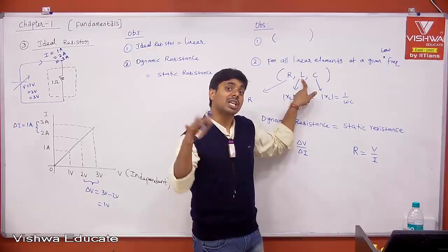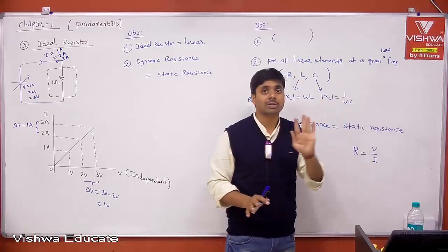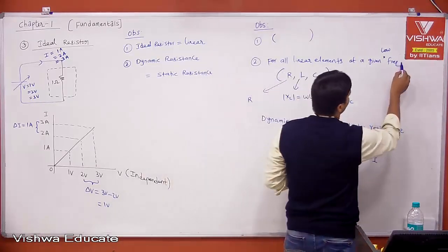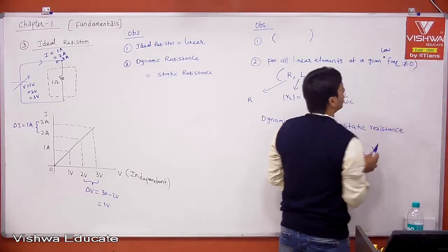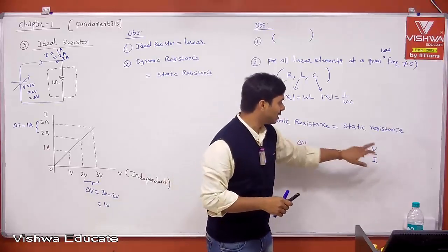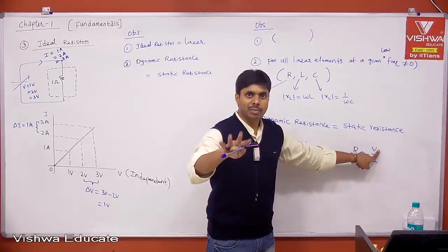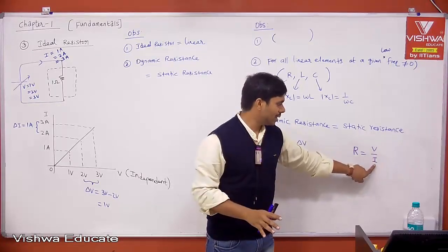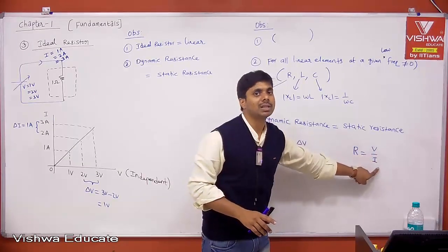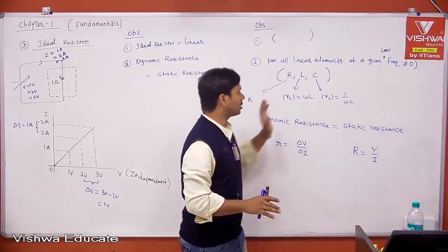To not have the special cases at zero frequency, I specified a given low frequency, but not zero frequency. Maybe if you want, you can say, which is not zero. Given low frequency, but not zero. Okay? Then, if you take inductor, what is V1? It is nothing but AC voltage, but its frequency is constant, right? And then what is the corresponding I? Therefore, this is like phasor representation: phasor voltage and then phasor current. Only for inductor and capacitor, this is a special case, okay? Then this is what is valid.